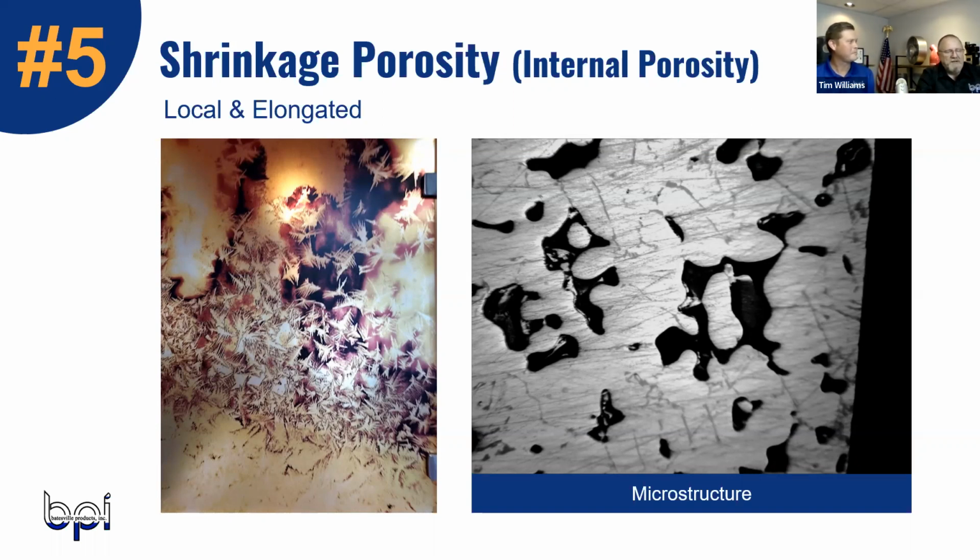It's more in the category of how your riser ring and gating is, depending on if your risers are working the way they should be. You shouldn't get too much shrink, but you still can. It depends a lot on the shape of the casting, and I'll let Ernie get in a little detail on this. But first, shrink is a solidification defect, and the only way to fix it is to freeze the metal or to feed it. So you have to get the metal there quicker, or you have to chill it faster. I'll let Ernie go into detail, because this is a very common problem, particularly on complicated or complex castings.